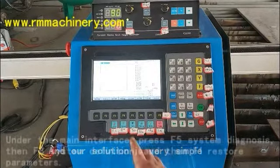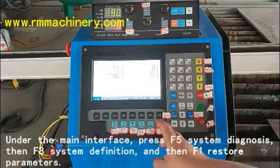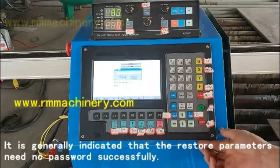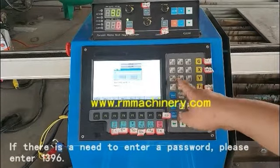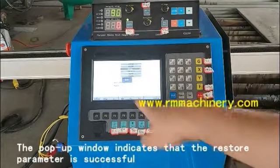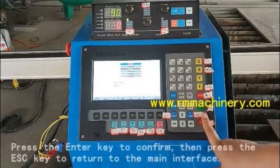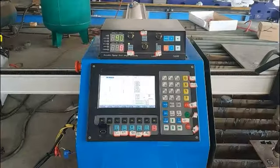In the main interface, press F5 System Diagnosis, then F8 System Definition, and then F1 Restore Parameters. Generally, restoring parameters succeeds without needing a password. If you need to enter a password, please enter 1396. The pop-up window indicates that the restore parameter is successful. Press the Enter key to confirm, then press the ESC key to return to the main interface.